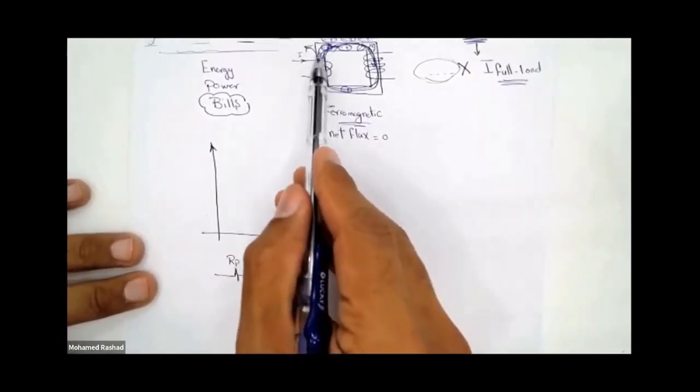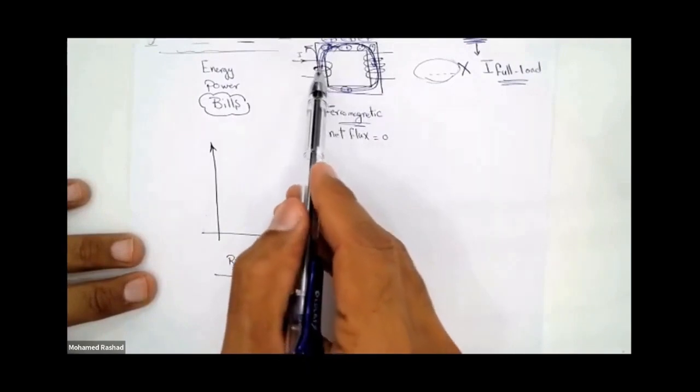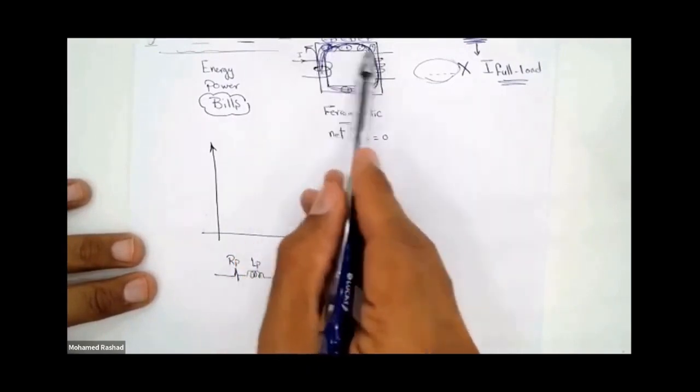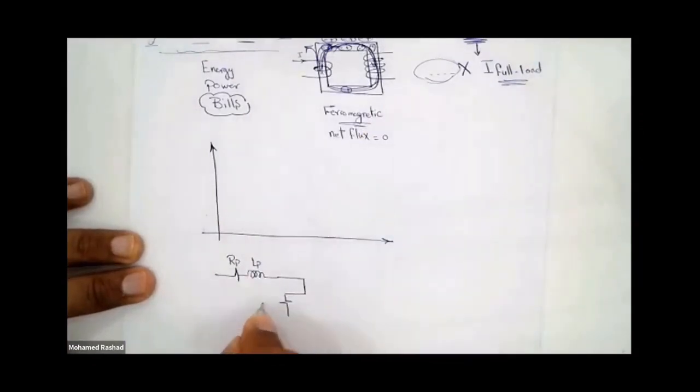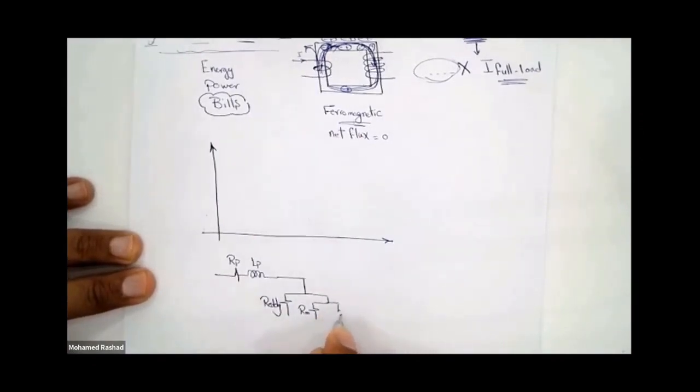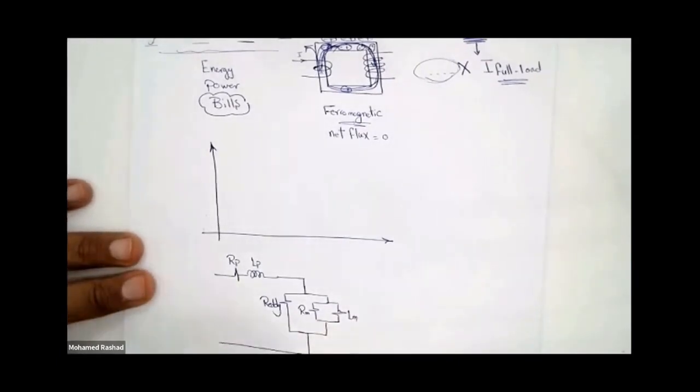So part of this magnetic field is converted into eddy current losses, and another part is used for magnetizing the dipoles. So you have two branches here. One we call R eddy, which represents the eddy currents, and the other is RM of the iron core. Very good, beautiful. And on the other side, I have the R secondary and the L secondary. So of course, when the primary current flows here, it transforms into the secondary current here.